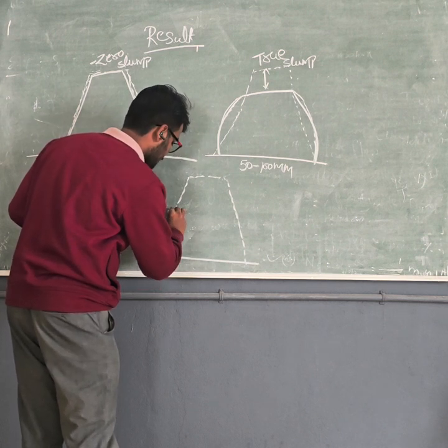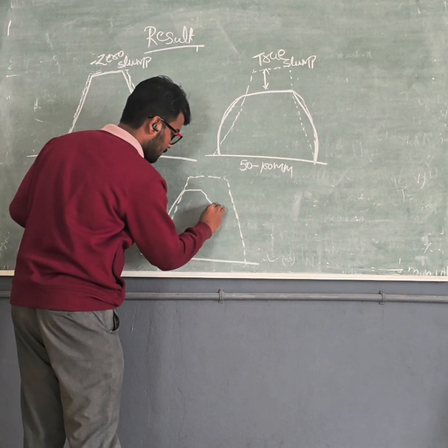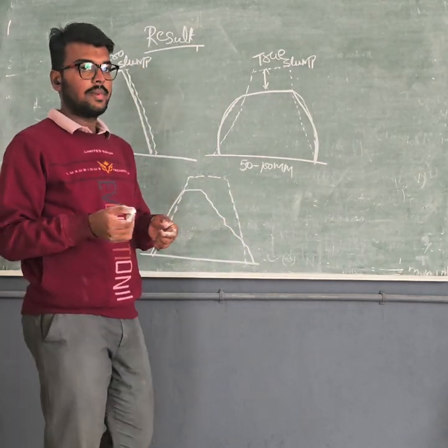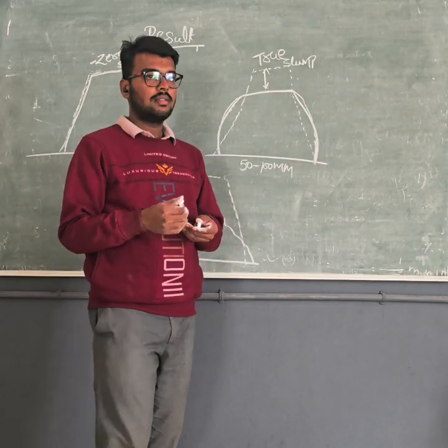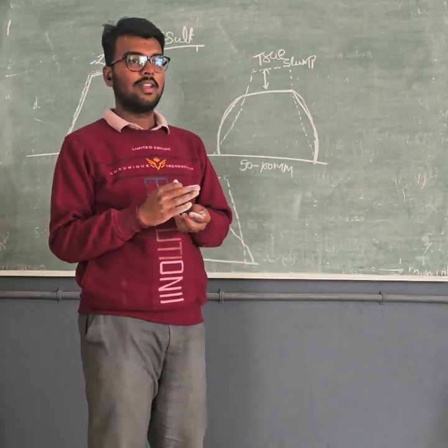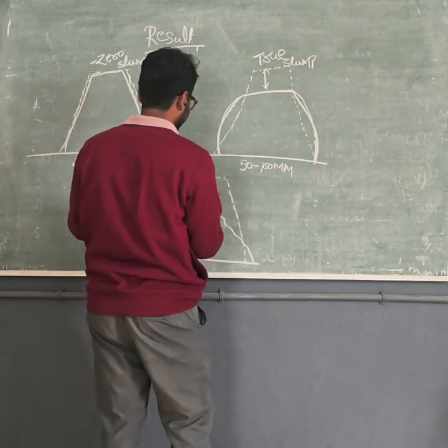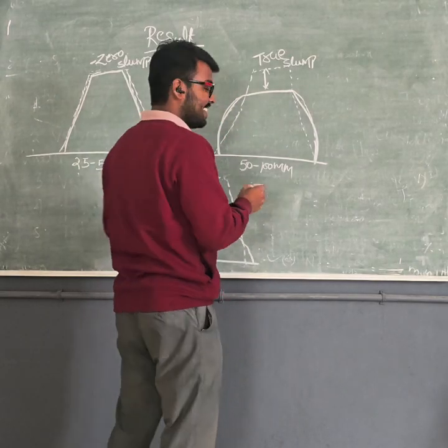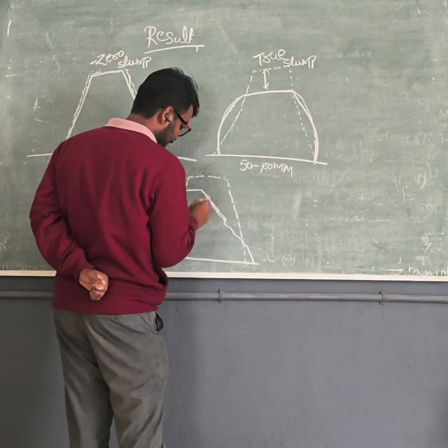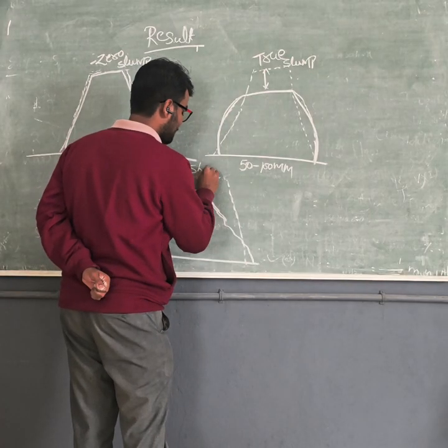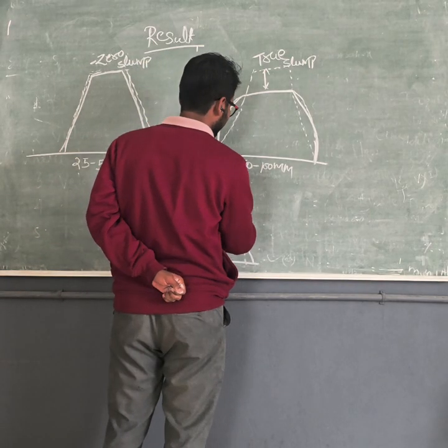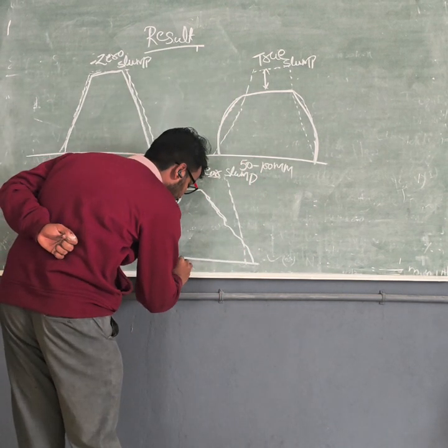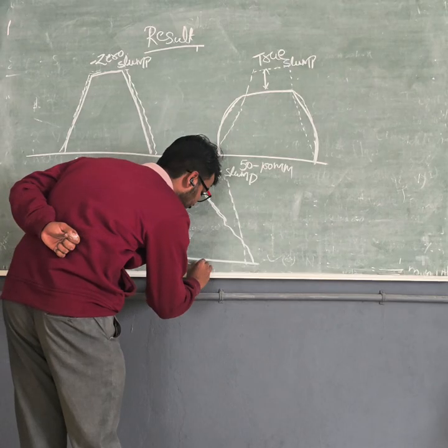It means one side of the specimen fails in shear force. This is the shear slump, and the value varies from 100 to 150 mm.